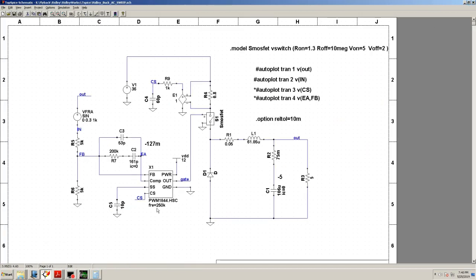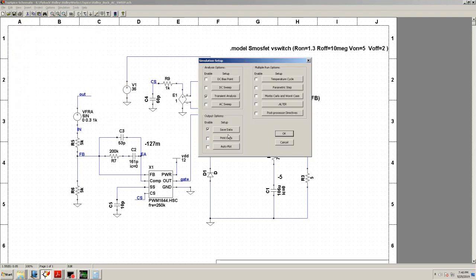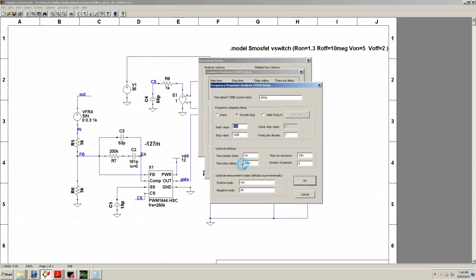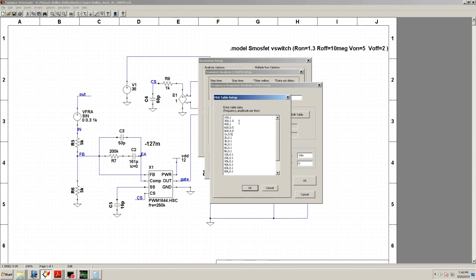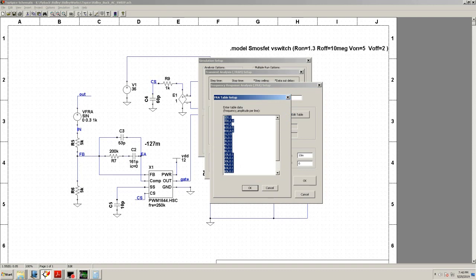That's one of the great features that was implemented recently, and that was by making this signal a variable amplitude. So what we can do is, in this case, we'll go to setup. Now we click table, and we can go to the edit. And if you're not sure if you can see this, the first line is 100 Hertz. I'm going to go ahead and take that off just to be consistent. We're going to say 100 Hertz.